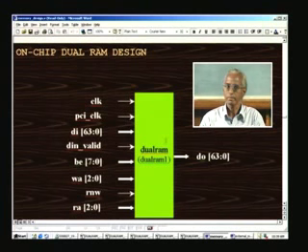And we need to write only 8 times, because what we need is only a block of image data, which is 8 by 8 pixels. Each of these pixels will be just 1 byte if it is monochrome. If it is color, it will be 3 bytes. Right now it has been implemented for monochrome, and you can always duplicate this dual RAM, triplicate rather, in order to achieve color motion picture as well.